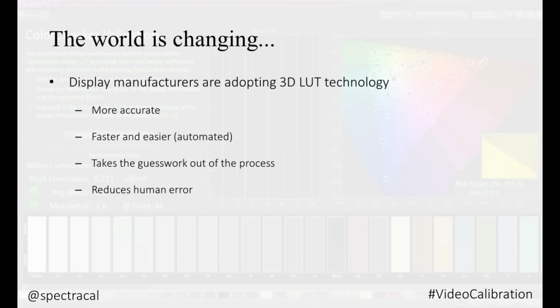You can set up the meter, set up your pattern source, select the particular LUT format, and push one button, and it will just run until it's complete. Take the file, load it into your application, your software, or your 3D LUT device, validate your color performance of your monitor, and then get back to work to the important things at hand.